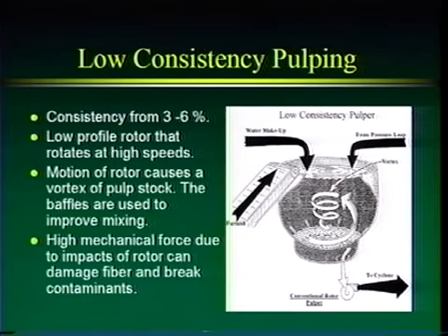Okay, so those are the three main types of forces in a pulper. They included mechanical action, the rotor acting on the paper fibers; hydraulic forces, liquid, and that liquid can contain fibers; and then attrition.